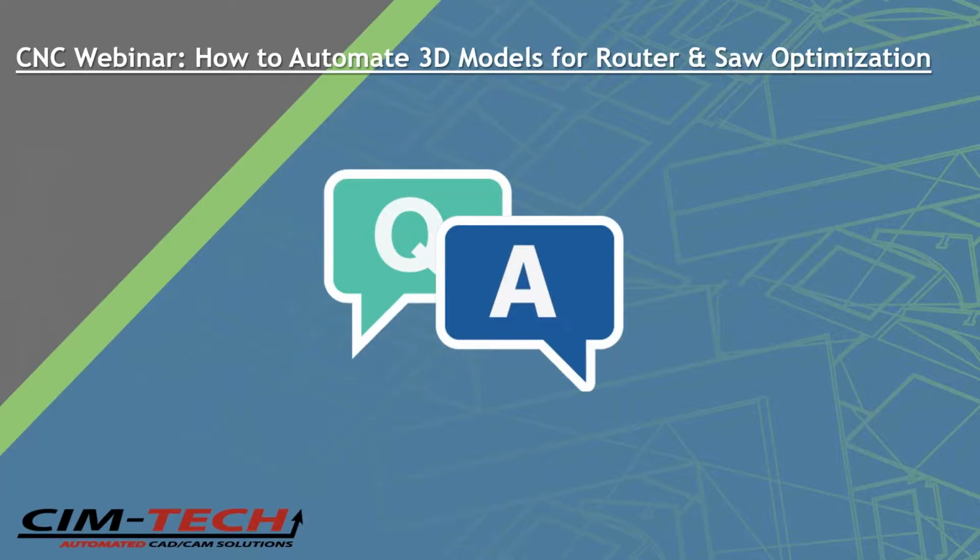It does, yes. Rhino is one of the many file formats you can import. When you start up AutoCAD, you type in import and you'll see Rhino 3DM files right there, and they import perfectly as a 3D model that's ready to go. So we can absolutely work with Rhino and many others.